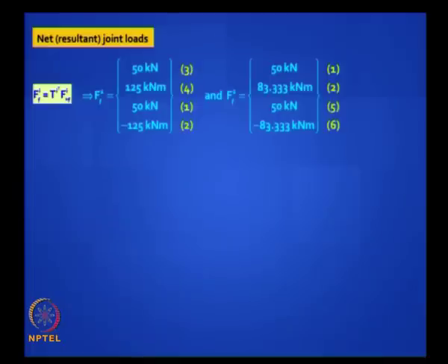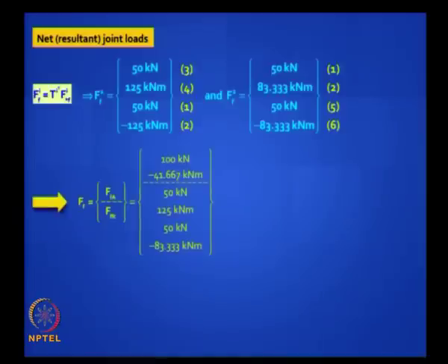So you have got the fixed end forces at the element level, you have to transfer them to the global level. So you have to just bring in those linking coordinates which we did, remember 3 4 1 2, 1 2 5 6, the numbers do not change because you are multiplying with an identity matrix. And then now you do the slotting. So 1 and 2 go here, 1 and 2 go here, so these will add up and you will get this, 3 4 goes here and 5 6 goes here. Does it make sense? That's something you have to do.